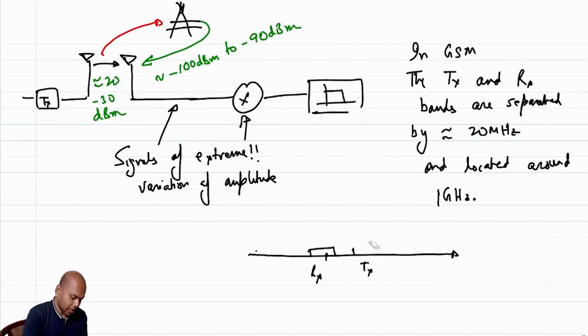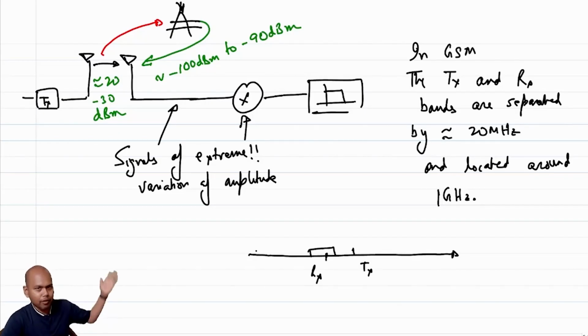And I know that the transmission power is generally much higher, because you are transmitting at the top of your voice, or another way to say it is that your cell phone is transmitting the maximum power so that the signal actually reaches the tower, which is probably 1 kilometer away. But the RX is getting a signal from some other tower which is another 1 kilometer away, right? So your RX is getting a very weak signal, but the TX is transmitting a very strong signal.